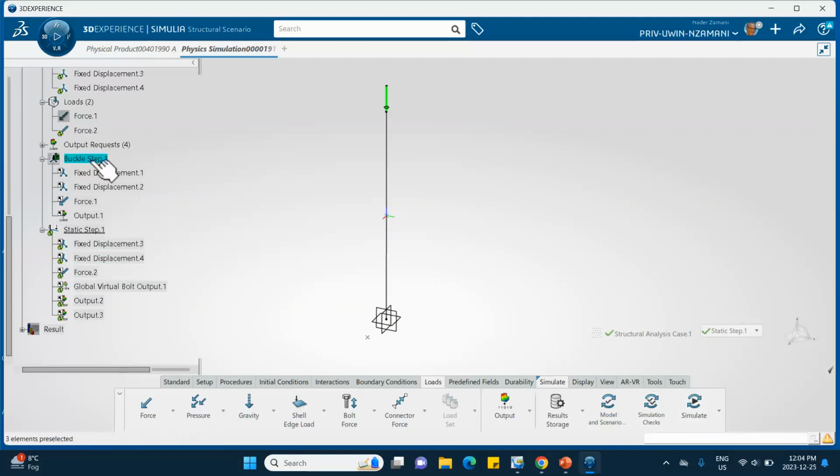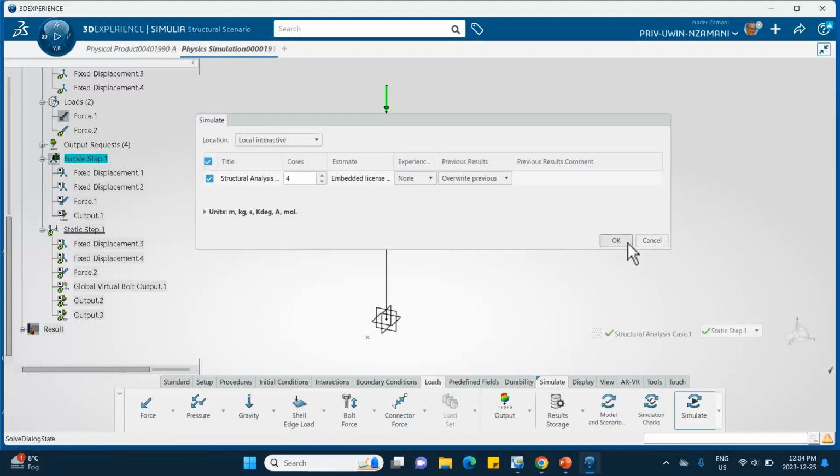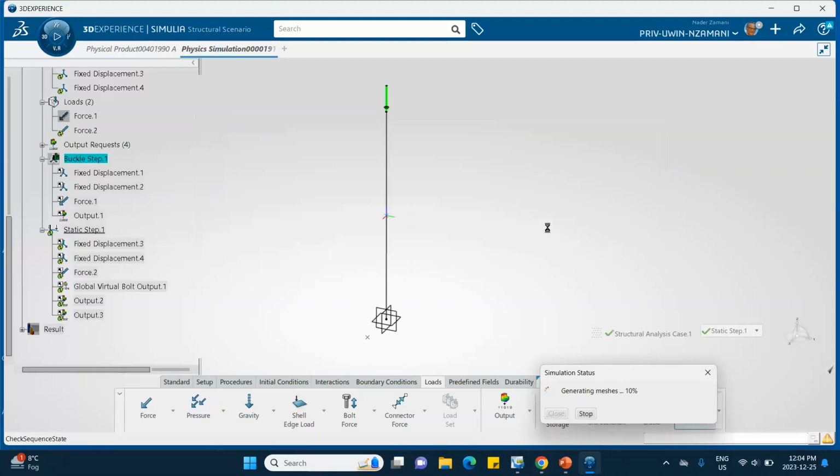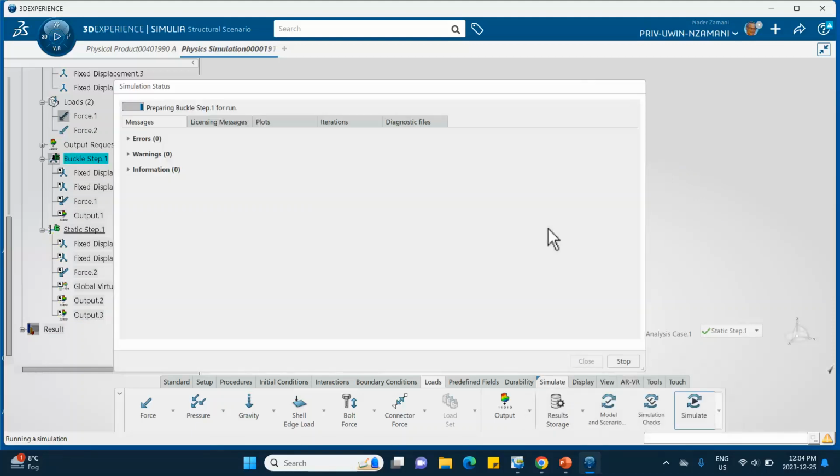It's going to run the buckling step again, which is totally unnecessary. That's why deactivating this would have been better. I just want the analysis of that portion. But because this is not deactivated and it's not deleted, it's going to do this one too. So let's go ahead and do it. And all we're going to see is the compression of that bar. No buckling at all. So the bar has no idea this was the buckling load. That has to be done a different way. That is going to be done in tutorial 6.